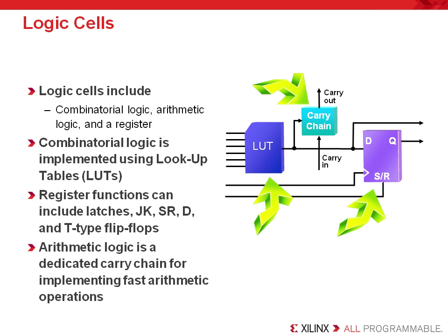Now, combinatorial logic is implemented with a LUT. Each LUT can implement any 6-input combinatorial function of your choosing with a constant delay. So you quickly realize that the complexity of the combinatorial function does not matter as long as the function does not require more than 6 input signals.